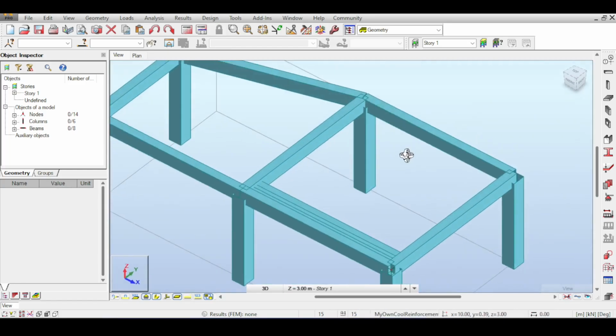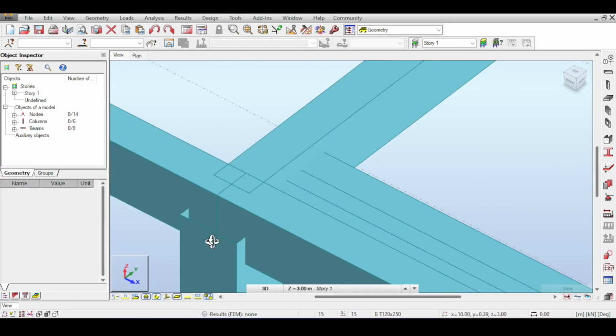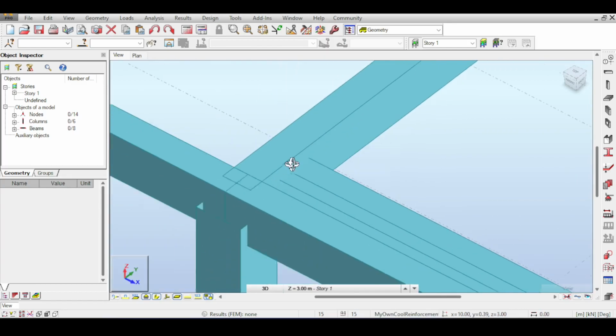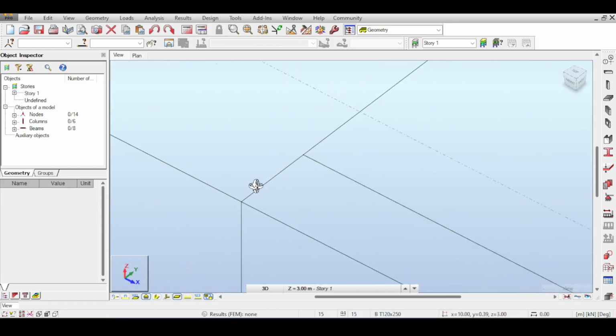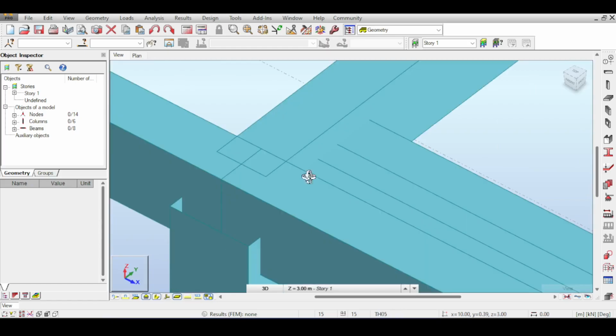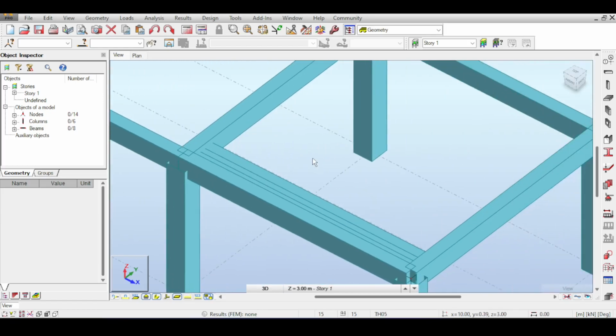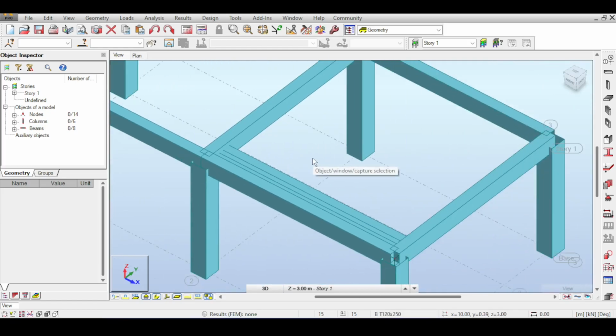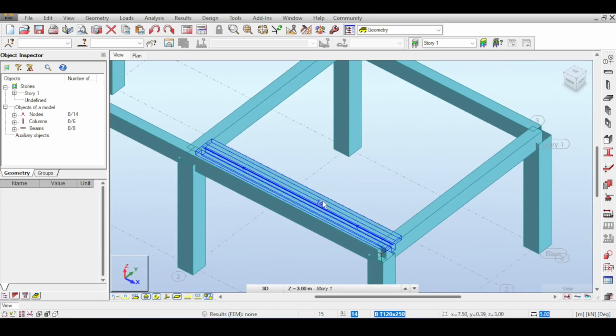But of course I need to continue my other ribs. Don't be discouraged by this little step you see here. This is finite element stuff. The finite elements need to be connected in the center. So this step is necessary for graphical interpretation. You don't need to offset that thing, because offsetting will cause the axial forces to cause moments, which is, of course, in our case here, inadequate.